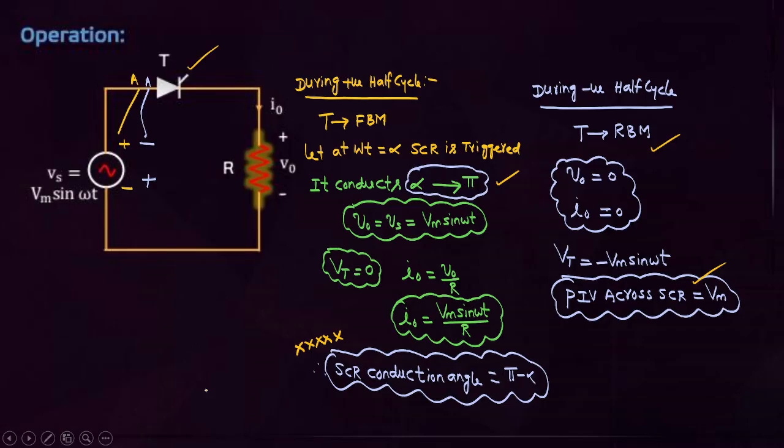Using R load, using resistive load, what is the SCR conduction angle? Pi minus alpha. Very, very important. What is the peak inverse voltage? For resistive load, half wave rectifier, peak inverse voltage is Vm.